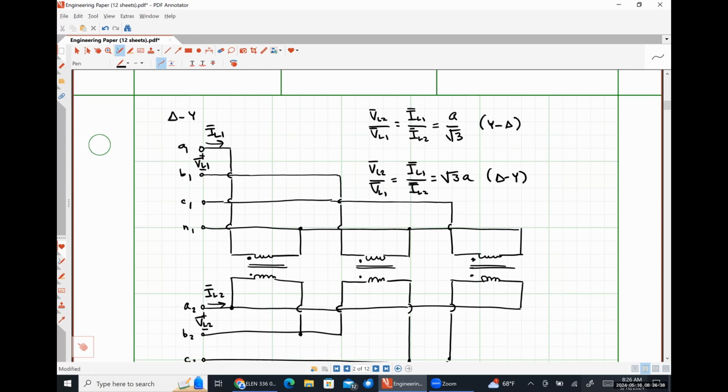In a real case, you're forgetting that wires have impedance, so voltage drops are going to occur over those wires. If you had a very large voltage drop over a very short section of wire, it's going to pass a huge amount of current, which is going to melt the insulation, cause shorts, and literally break the system down. That's why I say you're going to start a fire.